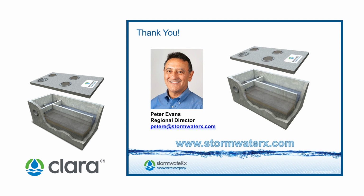We could only get what we got during the pilot testing, and I think the highest was in the 90s, but we did see good performance there. The expectation would be that treating over 100 milligrams per liter shouldn't be an issue. It'll just be a faster rate of solids loading into the filter. But the idea, as Peter said, of 100 milligrams per liter or above, I think would still be a good fit for the Clara filter.